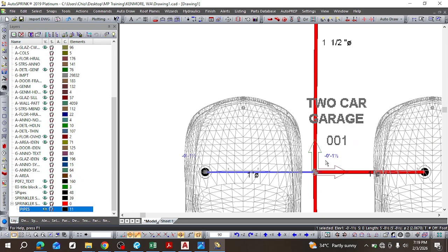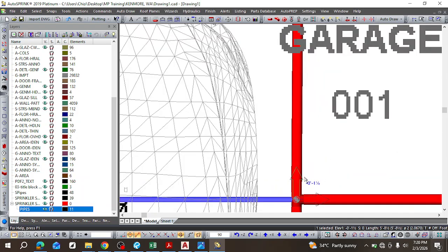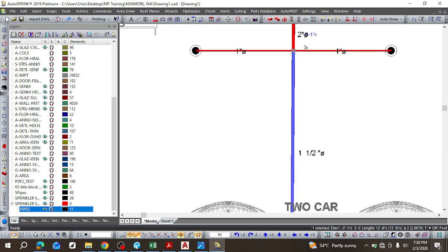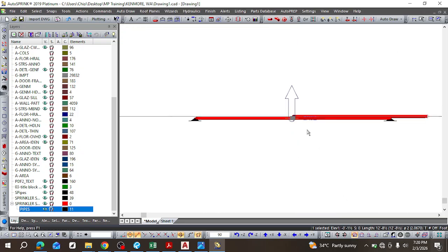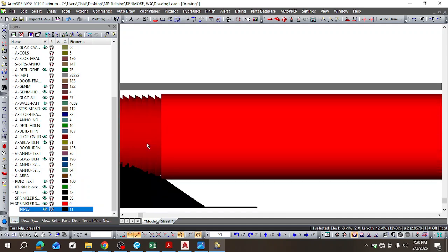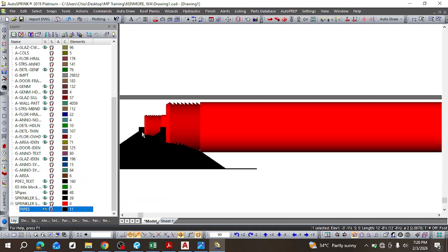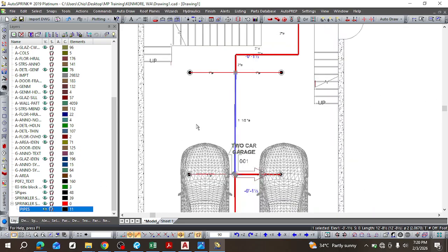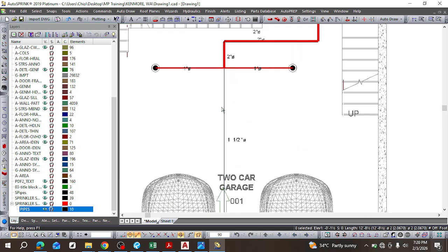Oh, you see, there's a problem. See this elevation. All the elevation should be on elevation 000 because it's flat on the ground. So there's a problem with this pipe because now it is not on the same point as the rest. If you look at it from maybe here, you can see that it is not all aligned, and that is a problem. Oh, we also have our fittings. We've added our fittings, it's not correct. That is a problem. So let's delete it and redo it. Let's check other pipes. See, this is a problem.